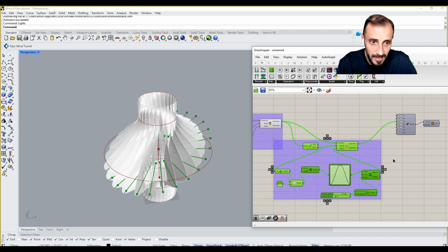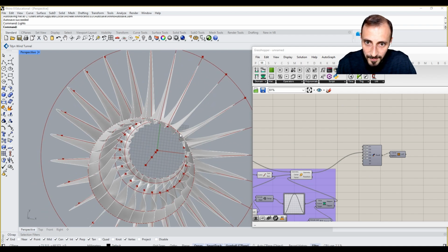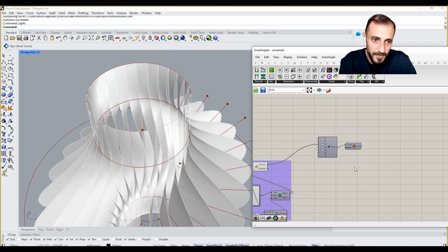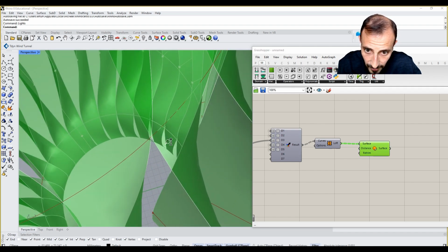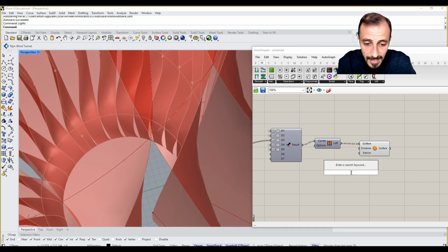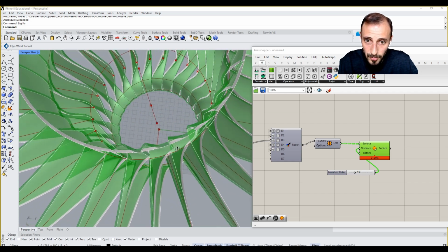And last but not least, I want to make sure this has some sort of thickness on it, like these stripes have some surfaces. So I'll be unrolling this. Oh, sorry, I'll not be unrolling, I'll be offsetting these surfaces. So offset surface, let's say this is my surface to offset. Probably it has now the value of 1, I think. No, distance is 0. So let's say 2.5 millimeters maybe. Is it too much? It might be too much, not too much.